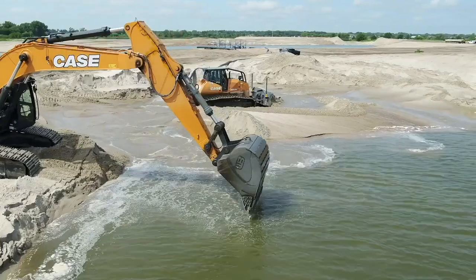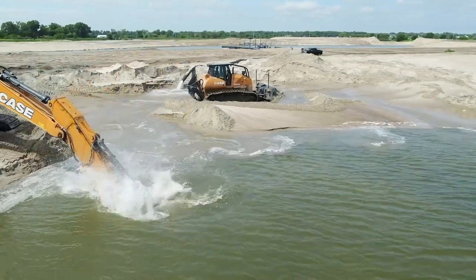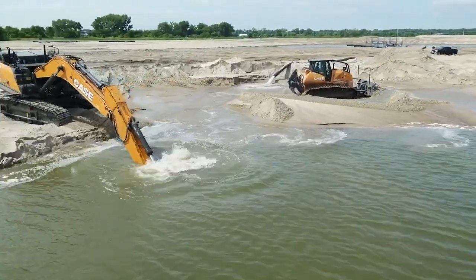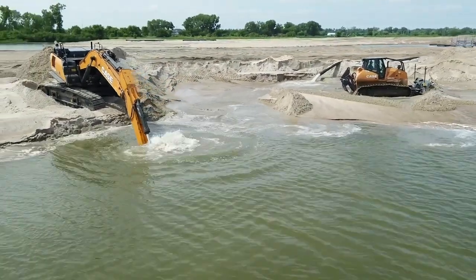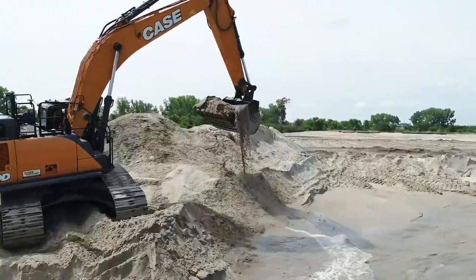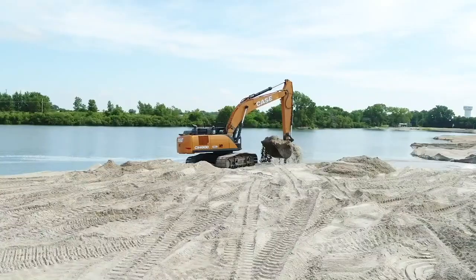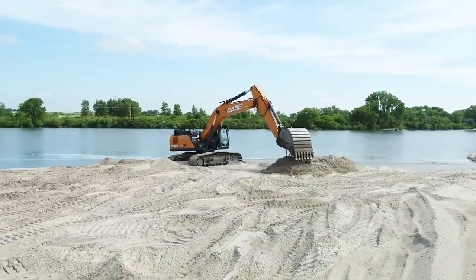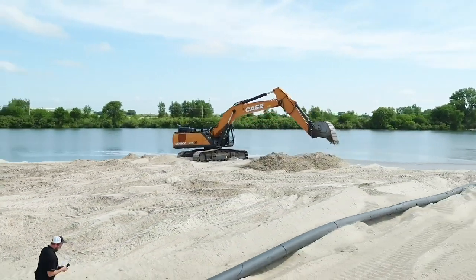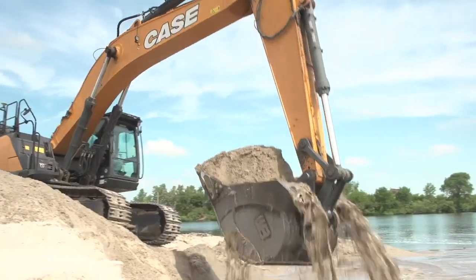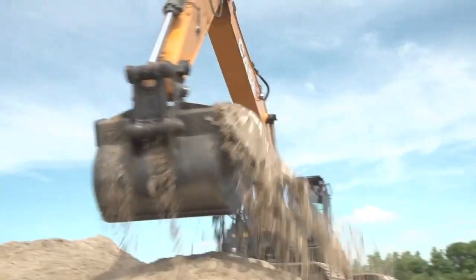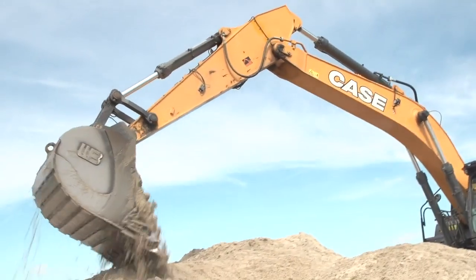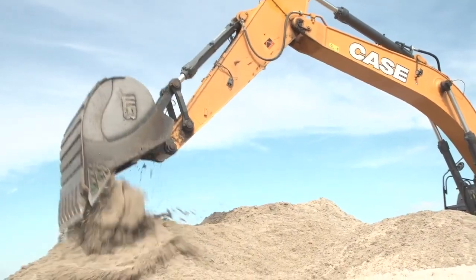Now that leads us into the next portion, which is proper sizing of the attachments. A lot of bucket options out there, right? And it can be confusing. One of the biggest things that we generally see is attachments that are too big for a machine. The reason for that is we always have changing conditions, right? If it's a real hard, dry type soil, you may need a toothed bucket that's smaller so that you can increase your breakout force. On an excavator, as an example, we want to keep that arm and boom and bucket function moving all the time and not stalling out.